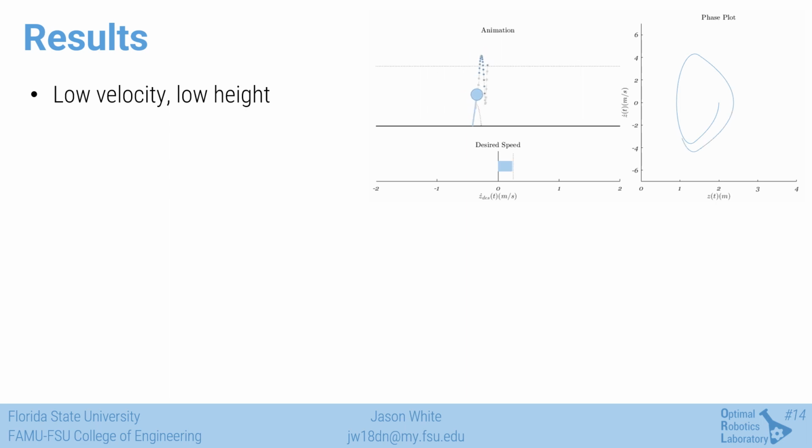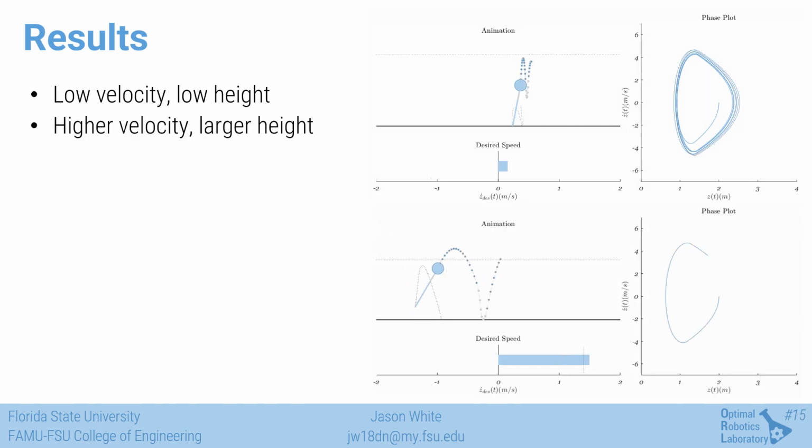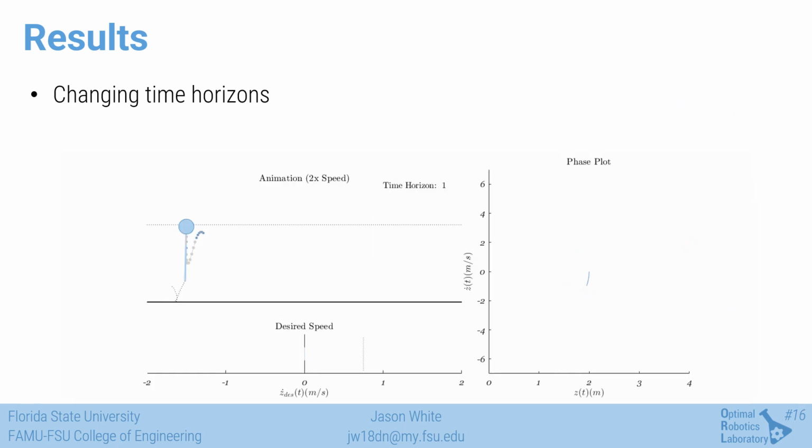The same behavior is apparent with the actuated spring mass model, which tracks the desired states at slow speeds and at higher speeds as seen here. Analysis of the exhibited gait cycles indicates that the key markers, such as gait period, are highly dependent on the dynamics and task, not controller hyperparameters such as the time horizon.